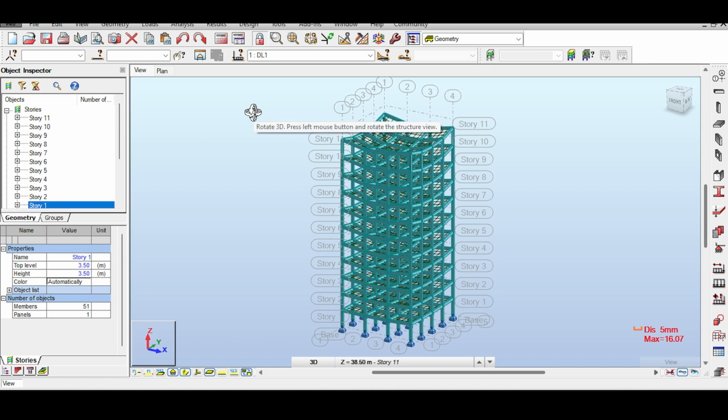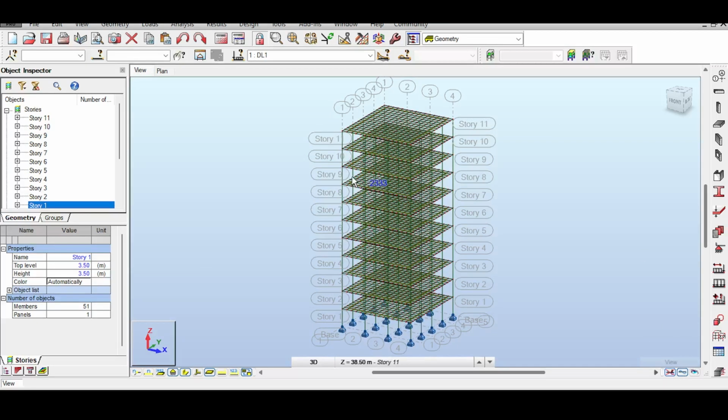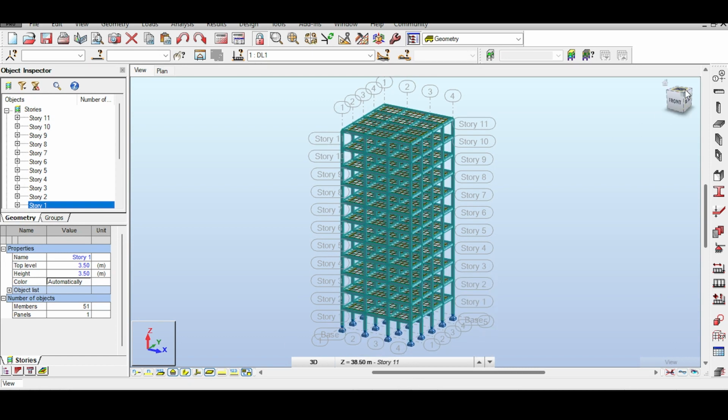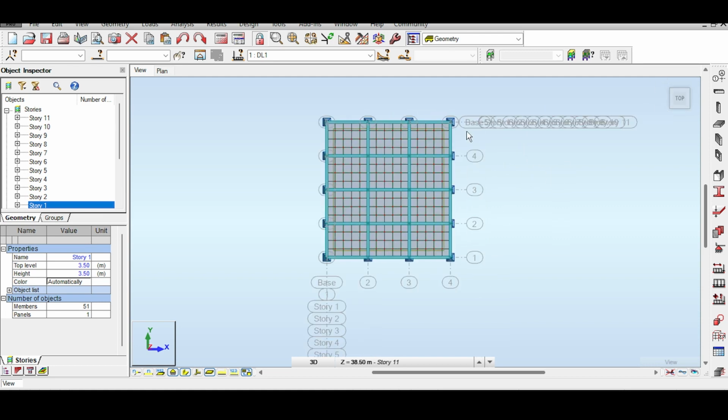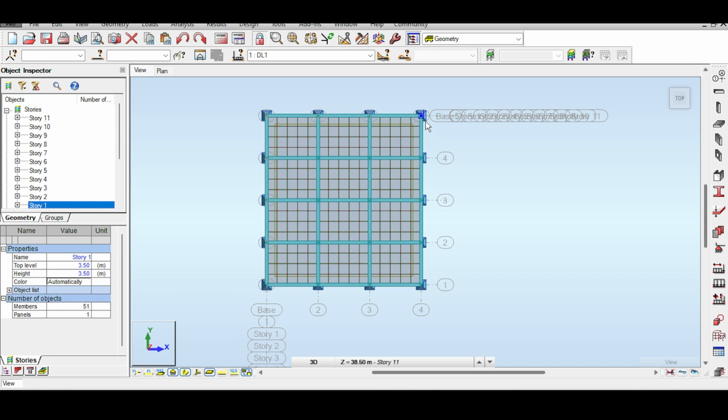Or so you thought, because in reality, vertical loads can produce sideways motion. And this is what happened in our structure. And to explain that, I need to show you a little trick. Now, I want to give you immediately the answer. The answer is there is a sideways motion or twisting motion or whatever because there is an unsymmetry in the abilities of the vertical load-carrying elements with respect to the center of gravity of the slab. This is the short and quick answer, but it would not be a CEE channel video if I don't dive into that. So let's dive into that.